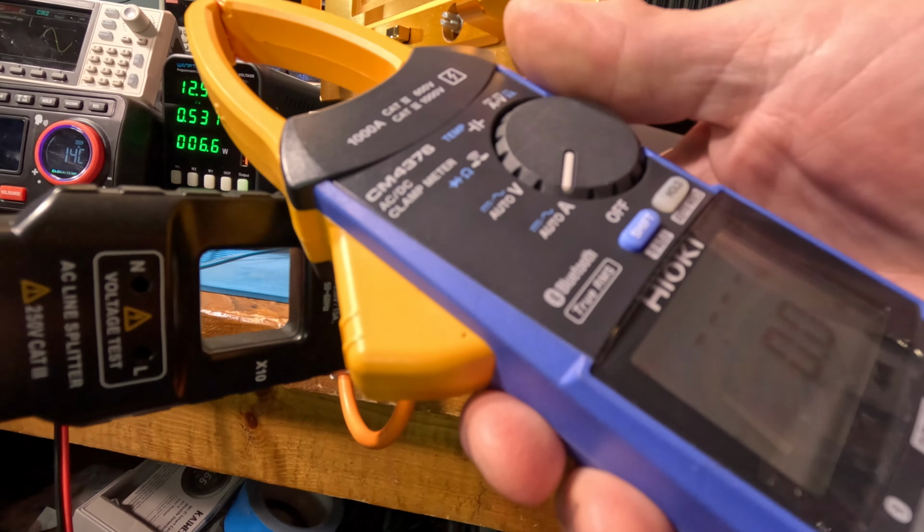Okay. So it's nice to have a little backup measurement there. But like I said, if we've gone to ×10, we just divide our measurements down by 10. And we probably get a little better accuracy because, right, looking at 1 amp on devices that are good for 500 or 600 amps. Yeah, we're asking a lot, but they're actually doing well.